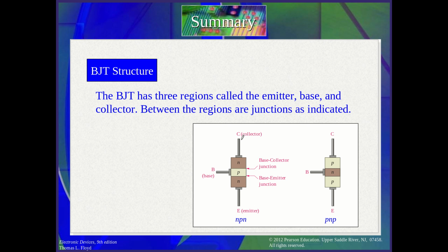One of the most basic tests for the BJT is to test the voltage in the PN junction between the emitter and base, and between the base and collector. It should be close to 0.7, and if you repeat it, you should see a value that is very close to the PN junction working voltage. Okay, and in the reverse you should see it reverse biased.